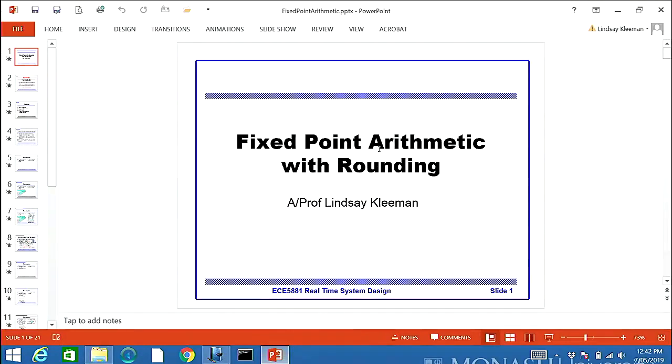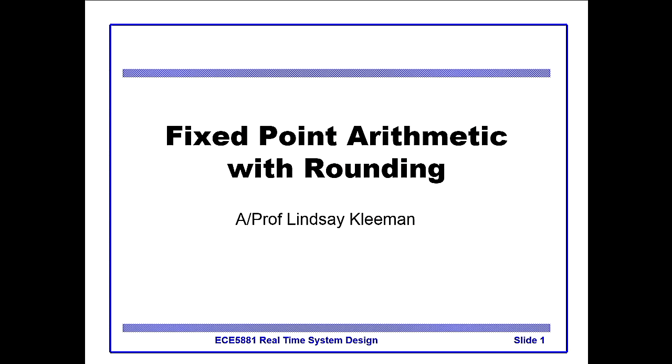So we'll come back to that one. So let's just briefly introduce fixed point arithmetic. We need this in the Pendulum lab, because we have to run this code for the PID feedback loop, which we'll talk about later. The proportional integral differential gain feedback loop for the control of the motor has to run really fast in order to keep up with the servo rate that we're looking at. So we need to avoid floating point arithmetic, and it's much faster to run fixed point integer arithmetic as a basis for real-time design. So often you'll find this topic comes up.